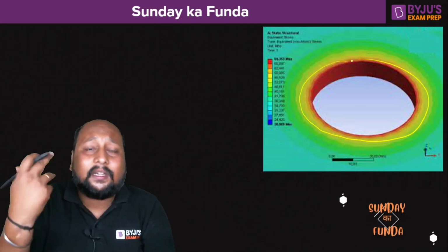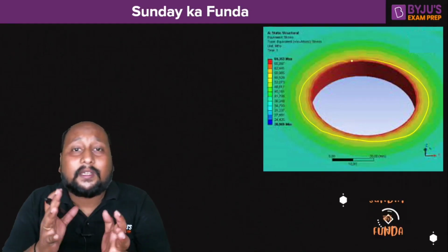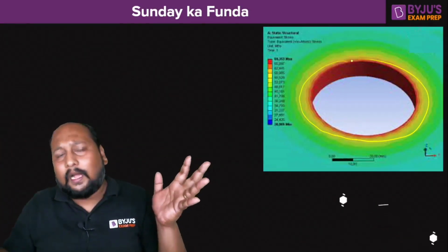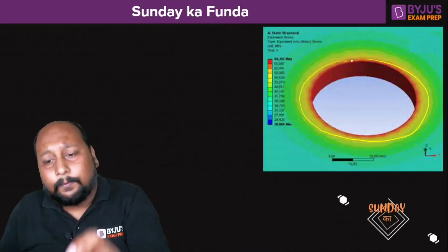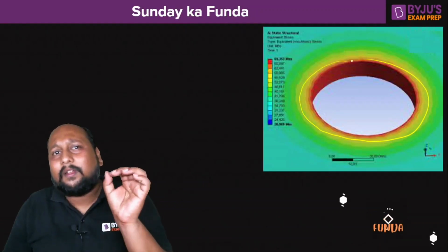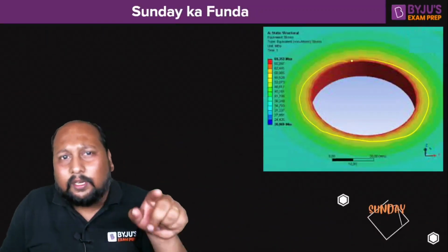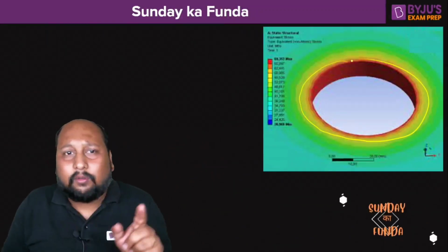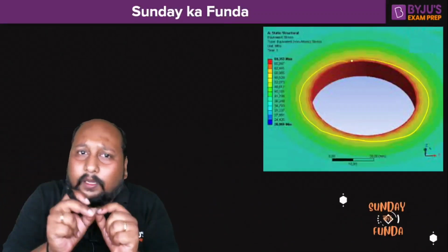If there is a stress induction, or we can say stress concentration, it won't have that much high stress concentration as compared to that of the round, right? Okay, so very important, very interesting concept. Why are we not providing a triangular or a rectangular shape, rather than giving a circular shape? The best reason is the stress concentration.